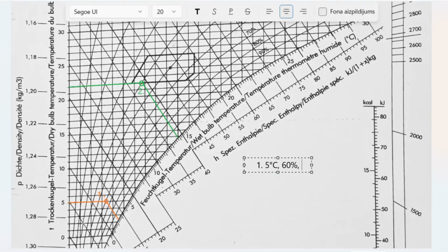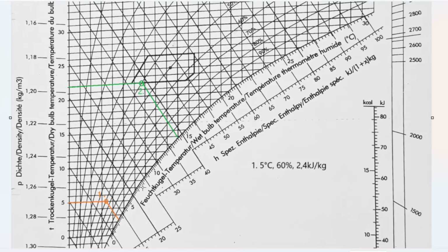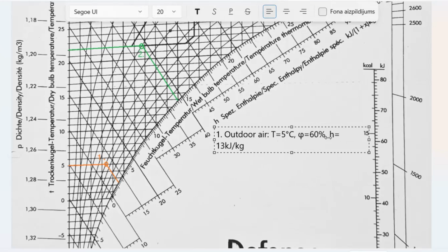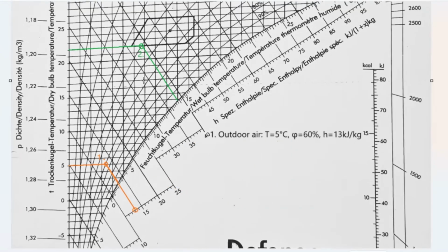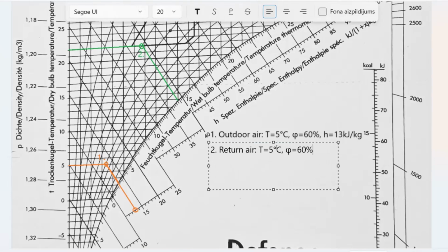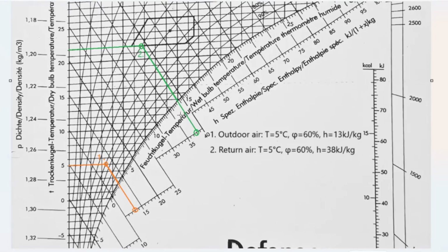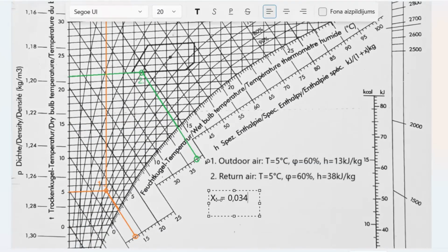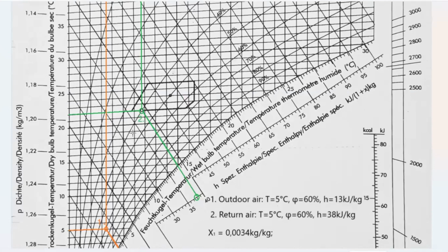Step 2. Plot the points. We'll use a psychrometric chart, also known as Mollier diagram, HX diagram, or ID diagram, to acquire the necessary air properties. This diagram shows relationships between air humidity, temperature, and other air properties. So I'm plotting those 2 points on the Mollier diagram. Let's go down via the enthalpy line to get enthalpies of this air, and we're going straight up via moisture content lines to read the moisture content in our parameters.